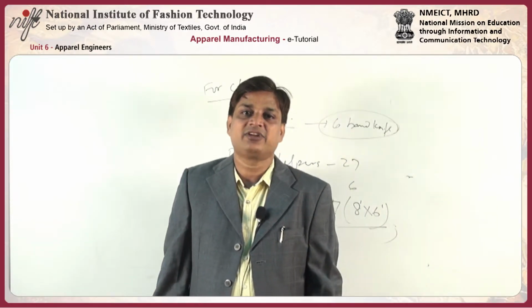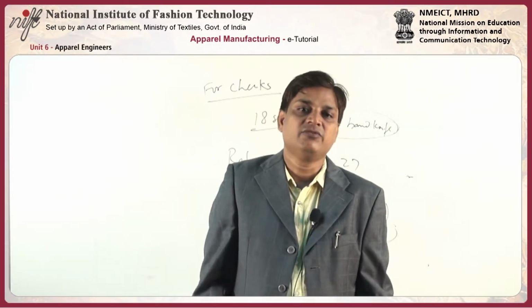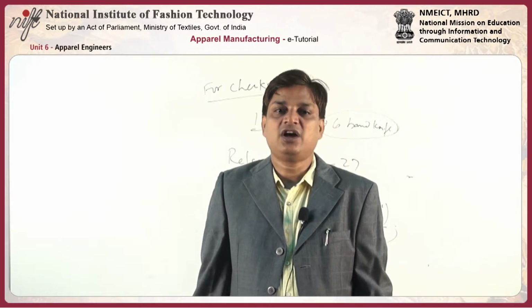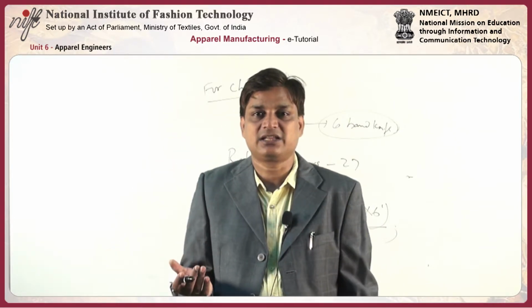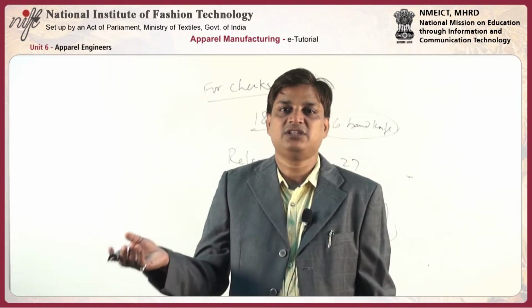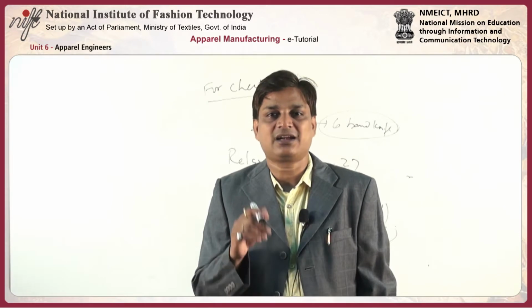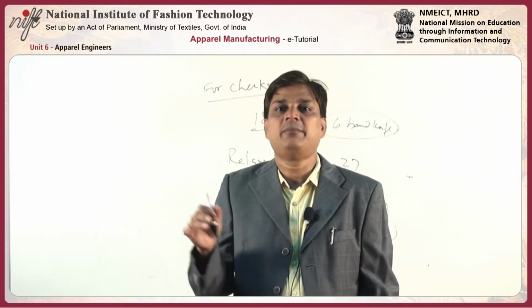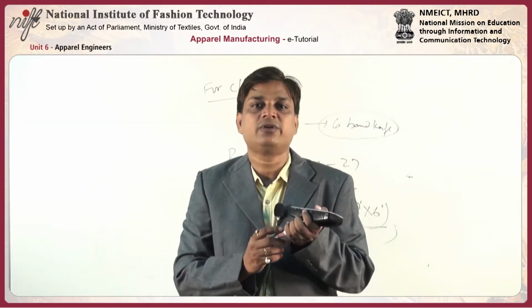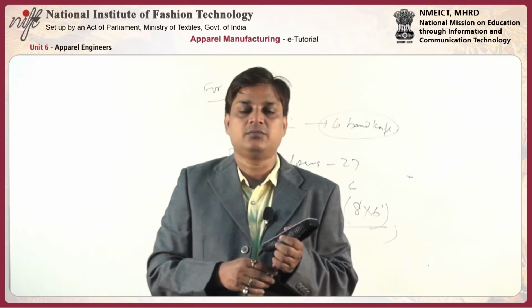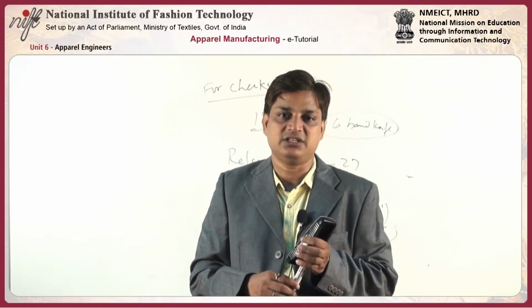Then we have die cutting. Wherever die cutting is required, we will use it. For smaller cuts, we need die cutting machines. The area of these machines we can get from the manufacturer catalogs, which give the area required for each and every machine. From the catalog we will add those areas and plan the cutting room layout accordingly.